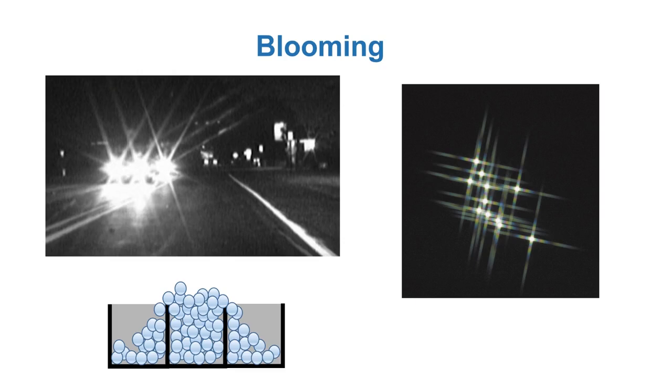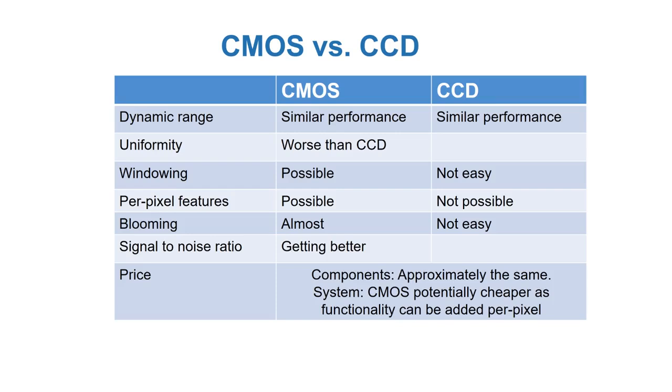Another issue to be considered when working with vision sensors is blooming, especially when the application is targeting nighttime capture. Looking at the images presented here, I think you're aware of the phenomena. Also for blooming, there is a large difference between CMOS and CCD. For CCD, blooming is often significant, especially for older cameras. This can be seen as the light-to-electron conversion overflow into adjacent pixels, here represented by the balls overflowing into the adjacent pixels. For CMOS, on the other hand, the individual pixels have their own readouts and very little, if any, such overflow.